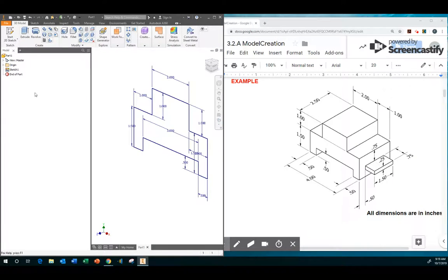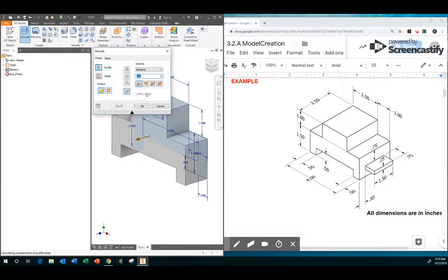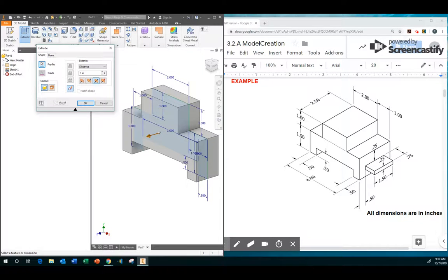You'll notice I did this all in one sketch. If you have more than one sketch, either you have a blank sketch or you do this on multiple sketches, you should only have one sketch so far. Now I'm able to extrude this. And I'm going to use a different extrusion just so you can see that there's different ones that exist. When I choose this button, it means that it's symmetrical, so it goes back as much as it goes forward. And I want it to be extruded.